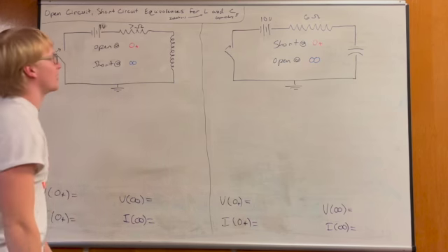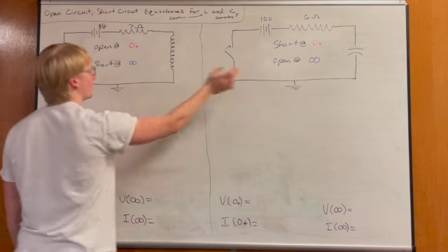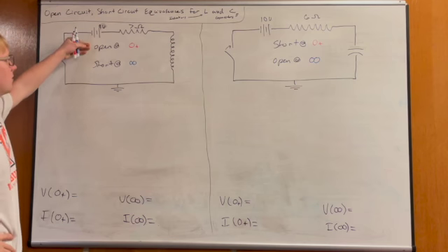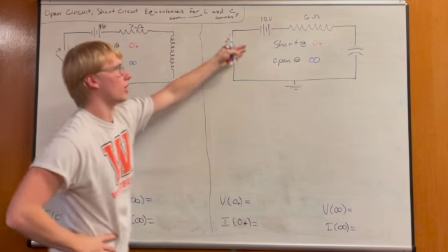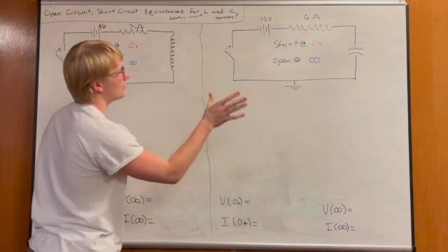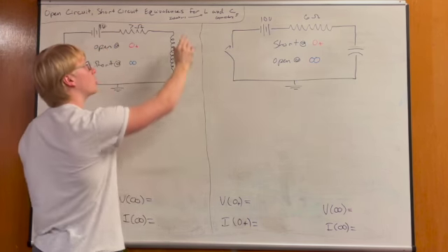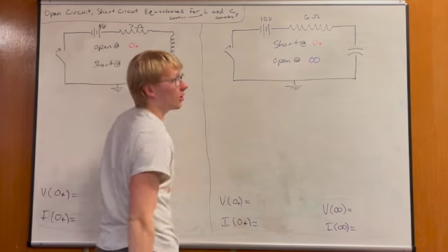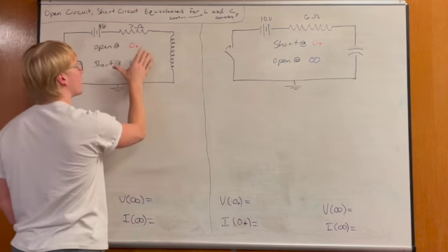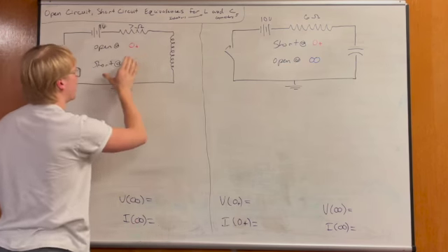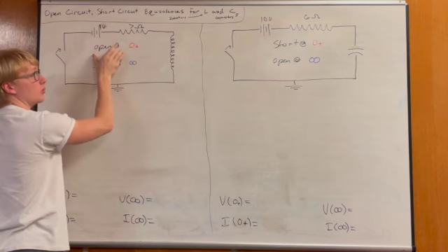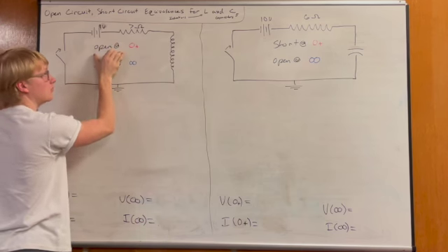Okay, so now I'm going to explain to you the inside of these boxes before I get into it all. These two rules are the main differences between inductors and capacitors when you analyze circuits like these. And so what this says is that for inductors, initially, we're going to draw them as an open circuit, as open.